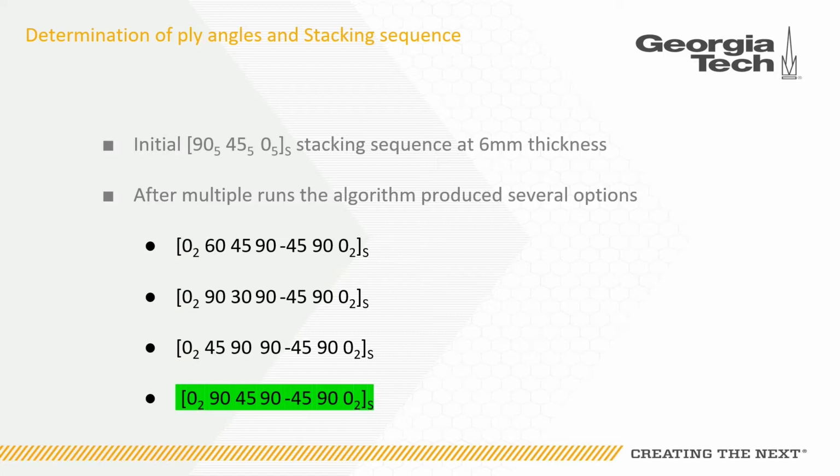It was determined that the initial stacking sequence was inefficient due to its high number of layers and high laminate thickness. To address this issue, we decided to add more ply angles, and the resulting stacking sequences are shown here, with the final stacking sequence chosen highlighted in green.